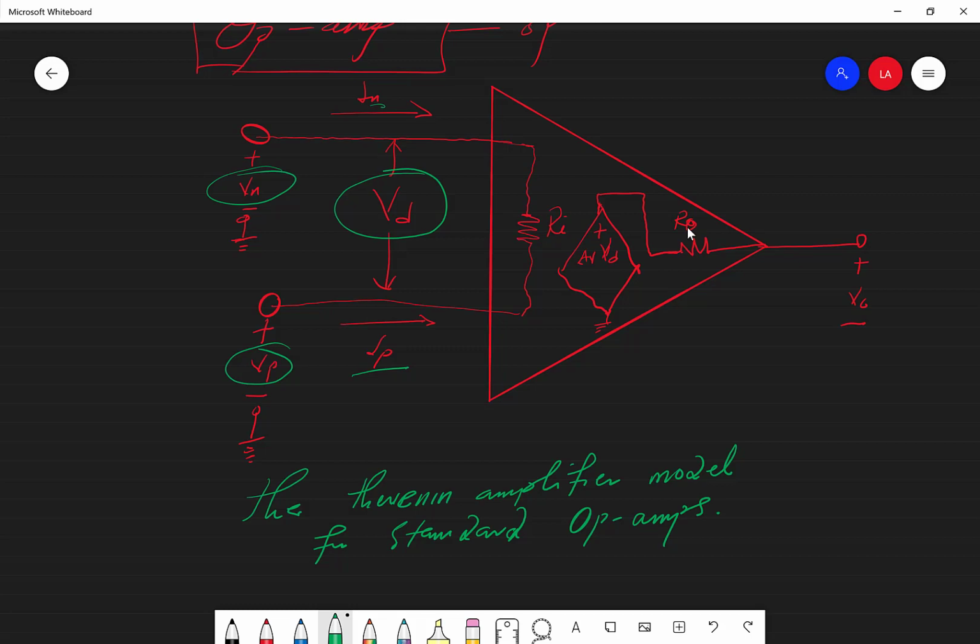all right. Now, an op amp basically is a differential to single-ended amplifier. Okay, you remember when we were looking at amplifiers in Electronics 1, we just drew it this way, where you had the input and then your output, which is just single-ended. However, an operational amplifier is a differential amplifier, in the sense that the input is the difference between the positive and the negative voltage. It amplifies the voltage difference between the positive and the negative.